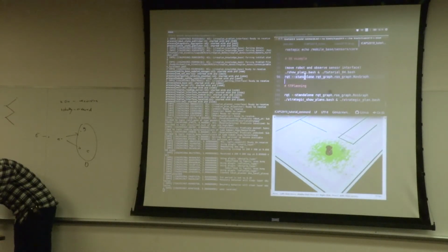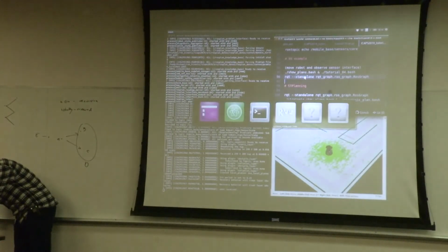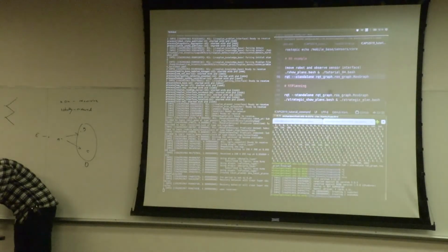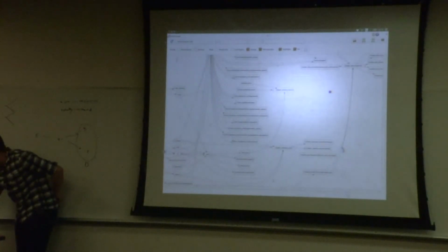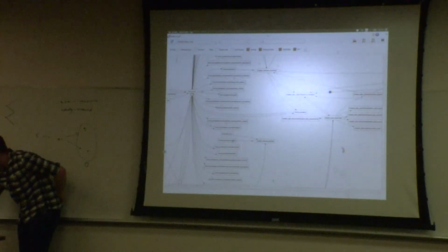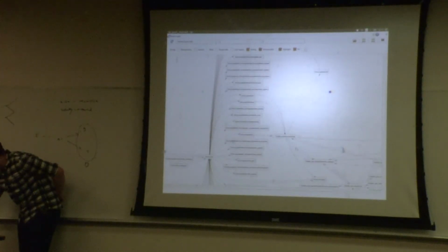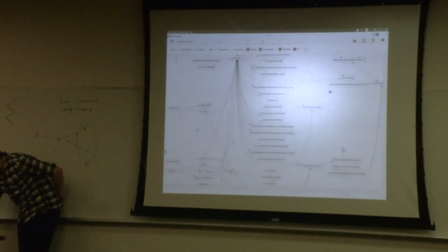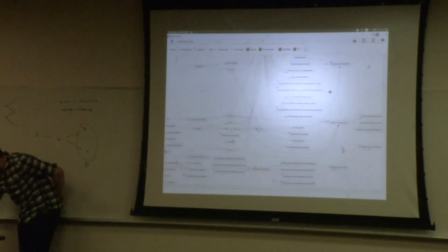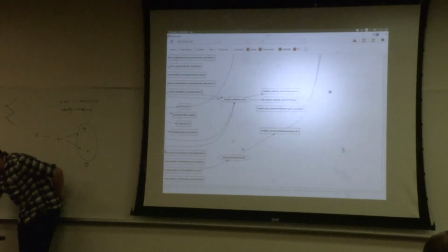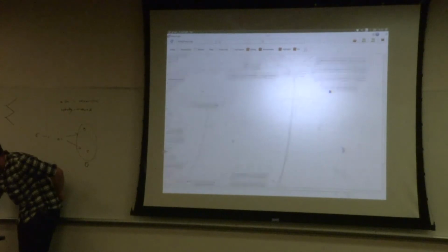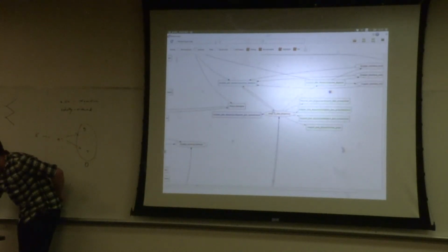I can show you the node graph once more before I run the... So this is the node graph I showed at the beginning with move base connected to the scan topic somewhere. And AMCL is running. And there is also now the ROSPlan nodes inside here. So we have the ROSPlan parsing interface here, publishing the complete plan, subscribed to by the plan dispatcher.